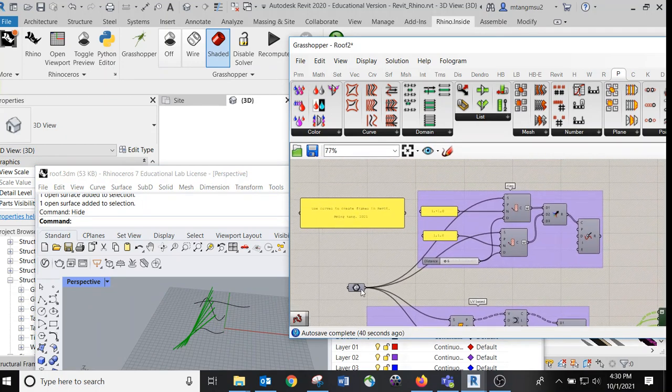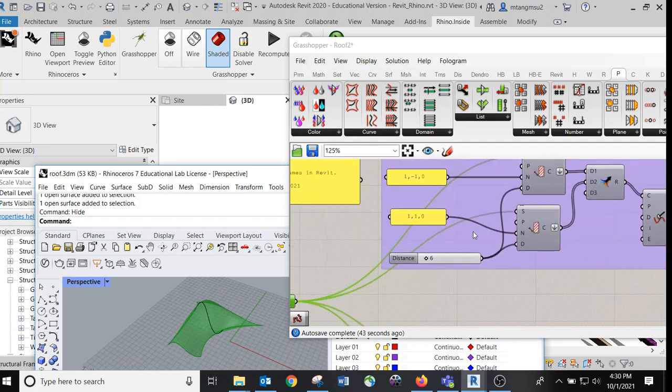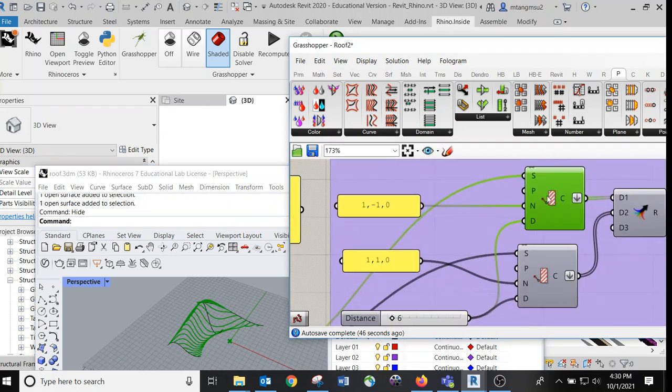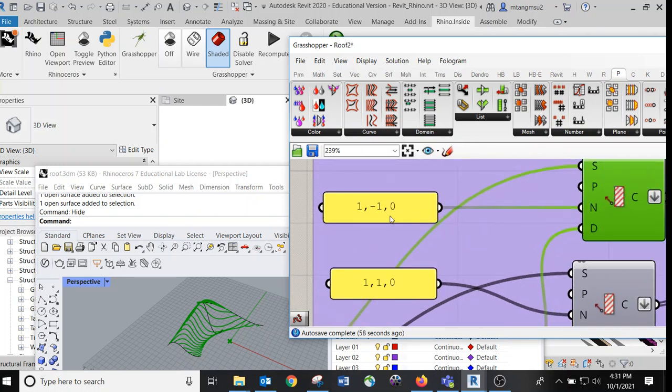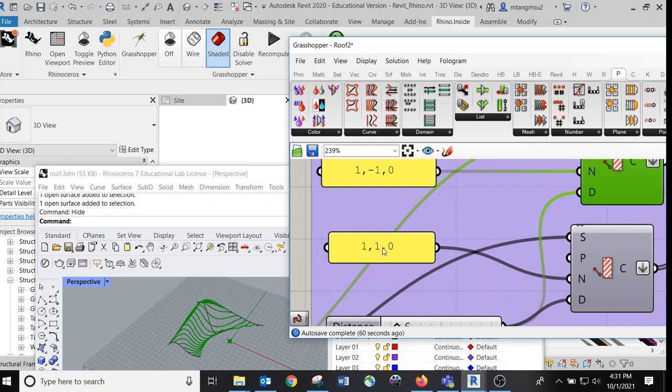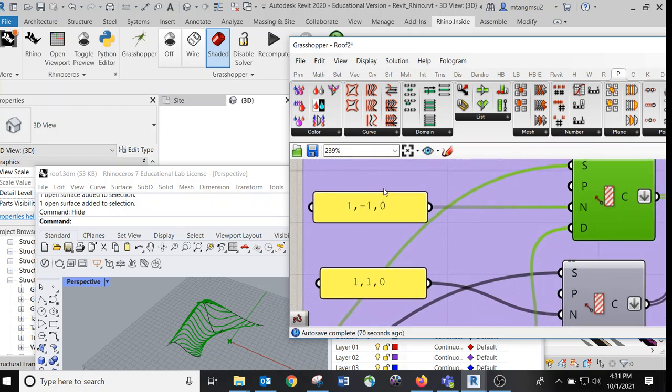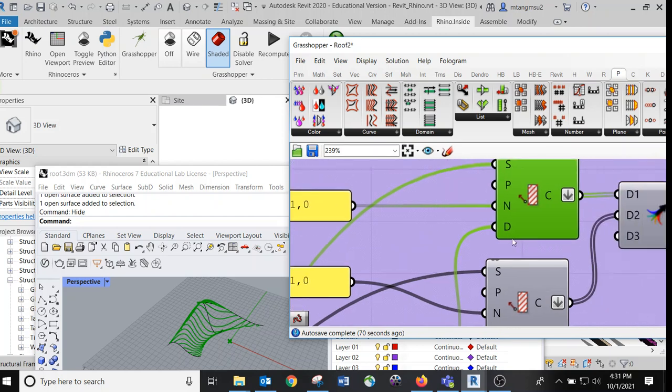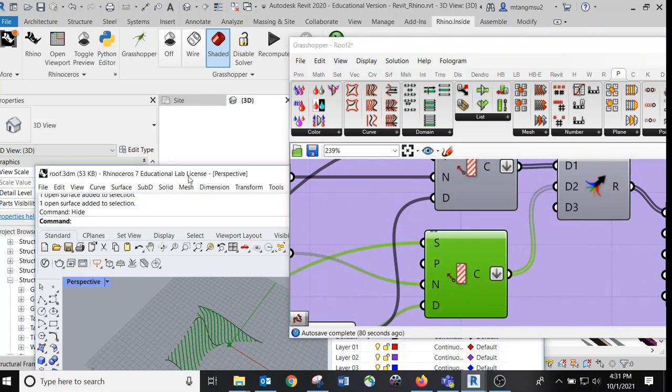Okay, so I will show you another really interesting workaround. If I have this curve again, right, and then I load this into contours. Contour is a quick way you can guarantee the line you cut is two-dimension. So basically, this direction is organized by x, y, z values. This is vector values. So if I want to go with a 45 degree in a coordination system, x is 1, y is 1, z is 0, right? So it's basically a diagonal line. But if you want to do the other direction, kind of like a mirror along the y, so you do 1, -1, 0. So by doing so, you can create two sets of curves.